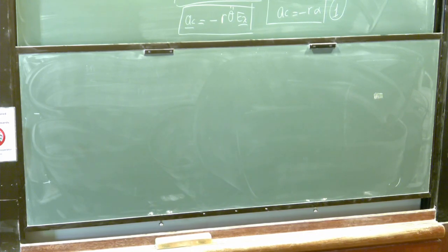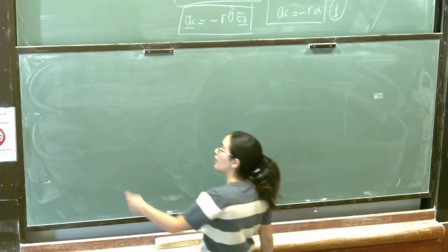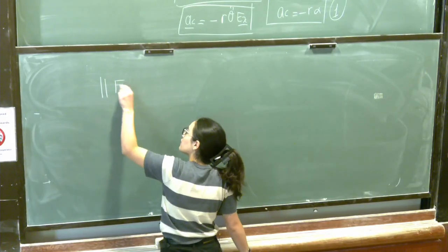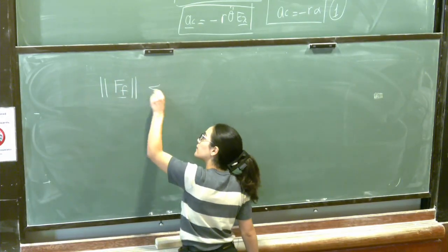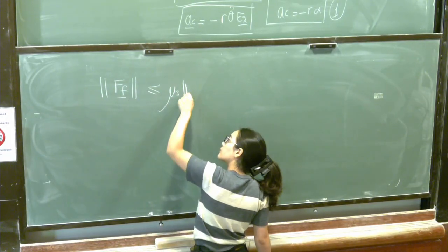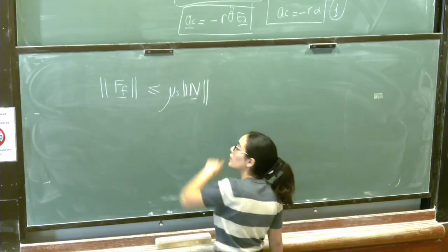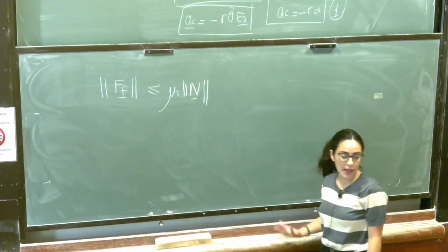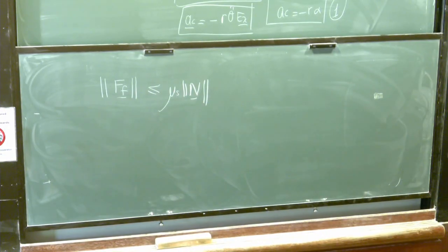Which inequality are you referring to? Exactly, the static friction criterion, that the friction force is less than mu s N. We have all the equations we need to calculate the friction force and the normal force. So using this inequality, you can find a minimum value for mu s. Make sense?